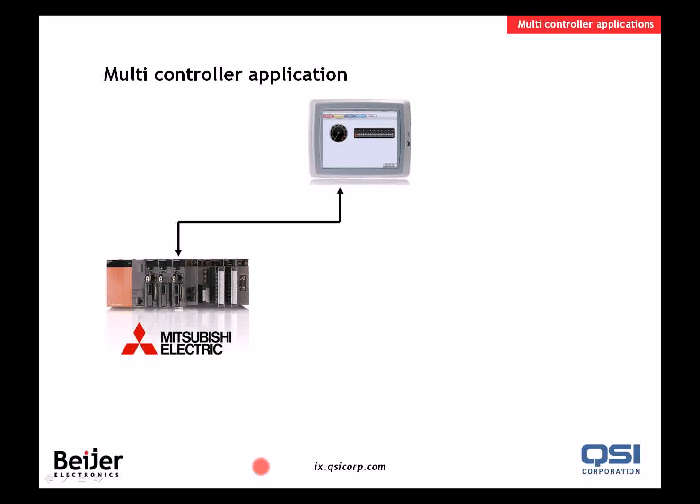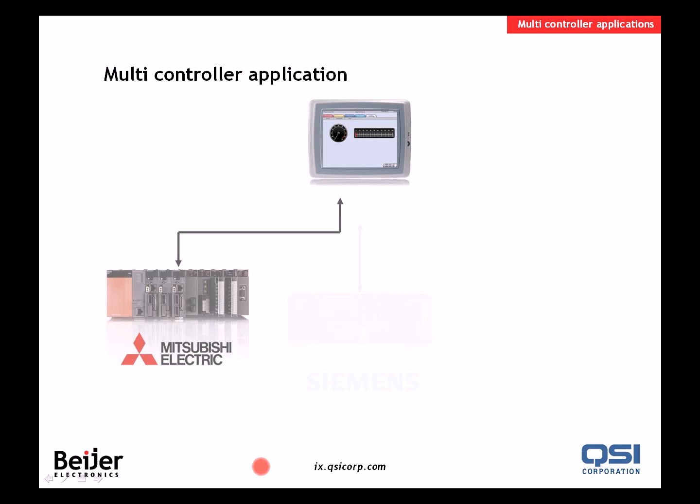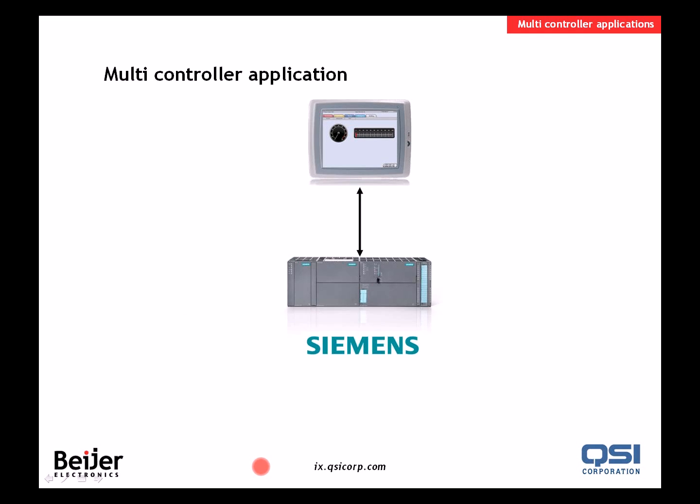So you can have an HMI application that you have configured to work with several different PLCs. And in runtime you can connect a Mitsubishi Q CPU, for example. And then you can just exchange this PLC for a Siemens S7-1200, for example. And just with a push of a button in the HMI application, you can switch the entire application to work with the Siemens instead of the Allen Bradley.